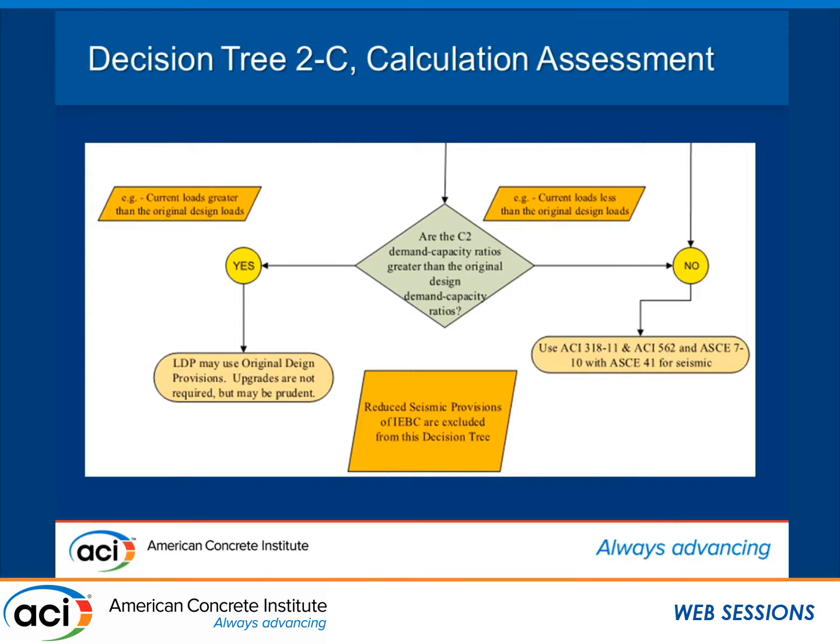I would look at phi factors in Chapter 5, and I would evaluate my structures using probably the phi factors in Chapter 5 and look at repairs. And the repairs won't make any difference. Chapter 5 is the same as 318, current 318. But it may help you on an initial evaluation of the structure when you get started looking at it. Okay? Thank you.